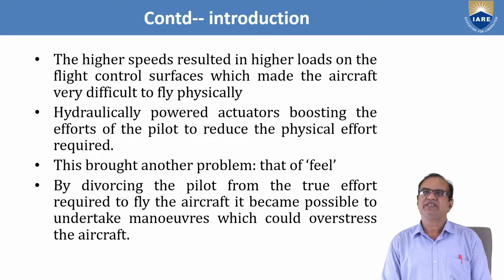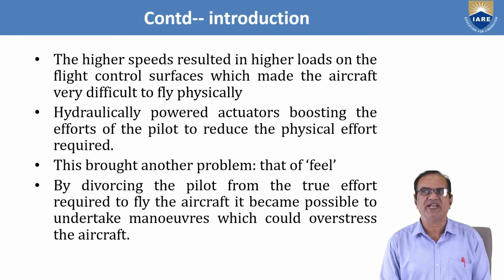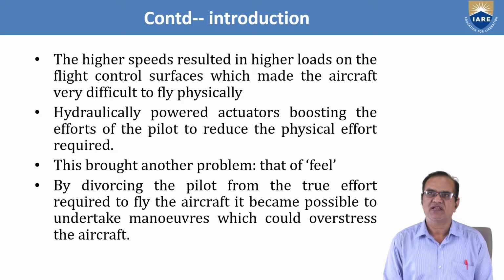The higher speed resulted in a higher load on the flight control surfaces, which made the aircraft very difficult to fly physically. Hydraulically powered actuators boosted the efforts of the pilot to reduce the physical effort required. This brought another problem, that of feel.